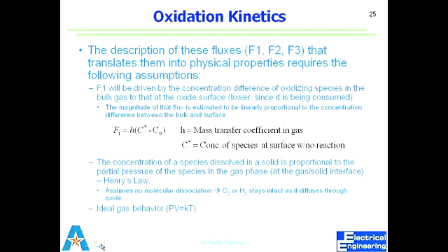If you cause them to break through electromigration, you're going to fry your IC, but the devices will still be good. That's why many times you might have two pins not working in an IC while the rest may still be working. Have you encountered that? Not yet. Yeah, that happens in the third world. I spent 10 years repairing those ICs on a ship, and we would look at which legs are still operational. If they are, we don't throw it away; we might be able to use it somewhere. So that's a sidetrack question.